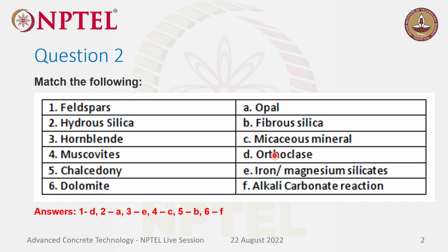So when you think about old structures, probably the water to cement ratio will not be that high. Recently only we are reducing the water to cement ratio to less than 0.5. Before it used to be in the range of 0.5 to 0.6. So when you have enough water for hydration, and you leave it for that long time, the fraction left unhydrated will be very less. And if it's a recycled aggregate concrete, and the fraction is not reacted with water, then obviously it has more chances for carbonation as well.